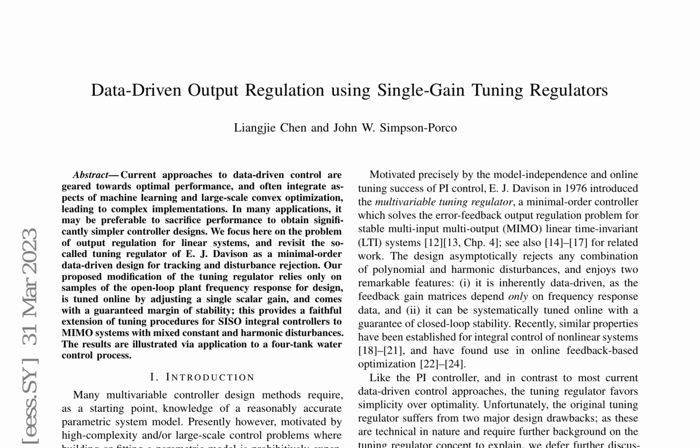Integral control eliminates steady-state errors in the system's response by using an adaptive internal model to track and reject disturbances. This approach is essential for achieving robustness in the presence of uncertainties. Adaptive regulation involves adjusting control parameters based on real-time measurements of the system's state, making it particularly useful for systems with unknown parameters. Techniques such as model reference adaptive control and adaptive internal model control can achieve adaptive regulation.